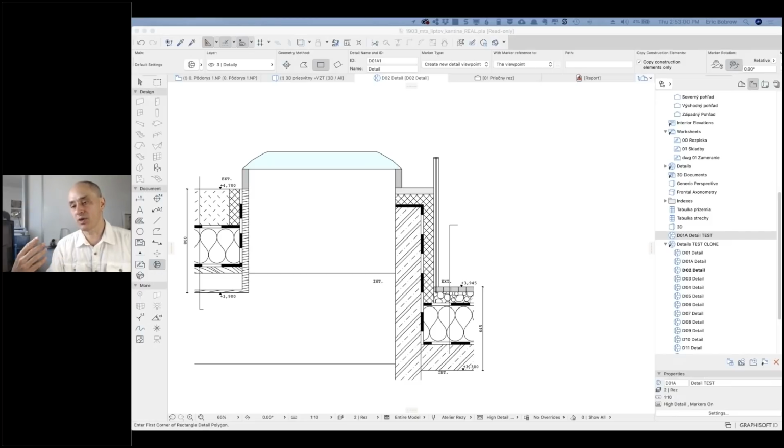And it's possible that clone folders, which are generally useful, can get confused if you want some details with existing and some details with new. I would say probably the general rule would be details should show the new conditions most of the time. So I would create the clone folder for the details with the renovation filter set at new, and that's probably going to serve you better. Okay. All right, so that's an answer to David as well as to your question, Andres. So thank you for submitting that.